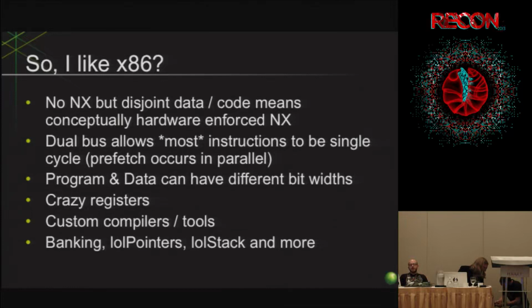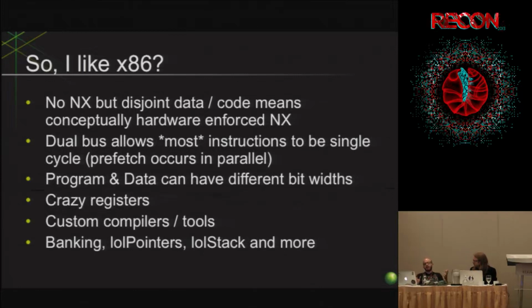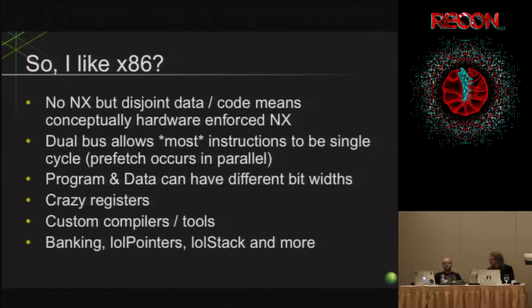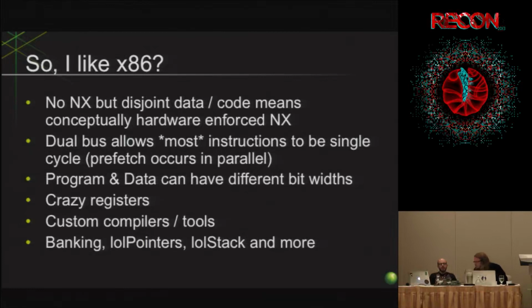When you're working in the Keil compiler or something like that, you have very nice libraries that magically make all that happen for you, and you never have to think about it much. You just call the right function and it happens. But if you're down in assembly writing shellcode, suddenly it's a huge pain, because the compilers naturally keep track of the state of tons of things that you would now have to keep track of yourself and manually fix up. It's a totally different headache than in a normal von Neumann architecture, where everything's addressable and it's there. You don't have to do any special tricks to make something accessible at different times.